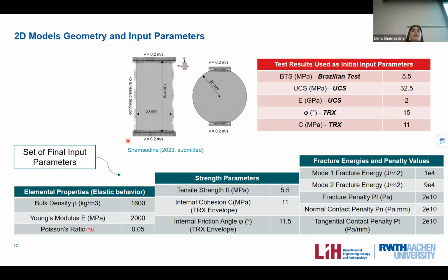This is the actual Poisson ratio of the 3D printed material. Because of the dominating axial compression happening in the samples, there is no radial expansion happening even close to the failure. We only have axial compaction because we have collapsing of the voids. And this results in a very low Poisson ratio, because the Poisson ratio is the ratio between the radial strain and the axial strain. So we have very low dilation happening in the samples because of the high porosity found in the samples.